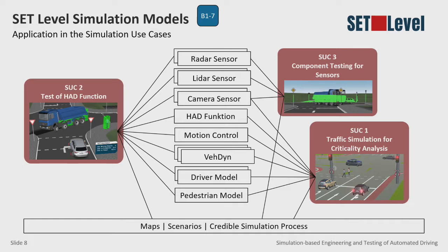And this is something we were again able to demonstrate as we have multiple simulations implemented. And also we see that different simulations have different requirements. That's, for example, the reason why radar, camera, and LiDAR sensors are not each modeled just once, but why we have two models for a radar and two models for a LiDAR, because one of them is object-based for when the sensor effects do not play a huge role in the simulation, and we have the physically based sensors, where it really comes down to the physical properties of the sensor and the technologies that are underlying here.